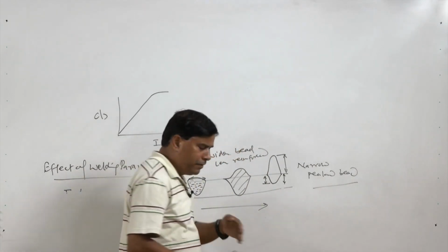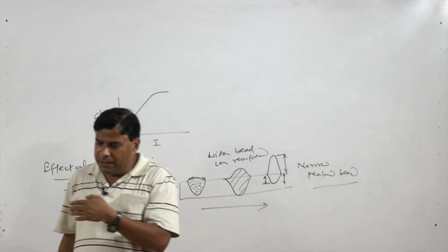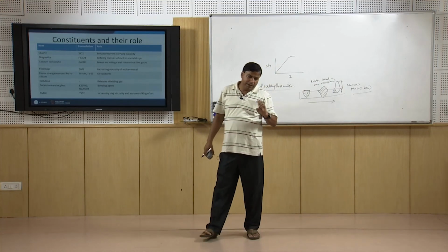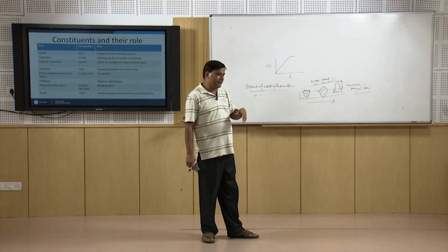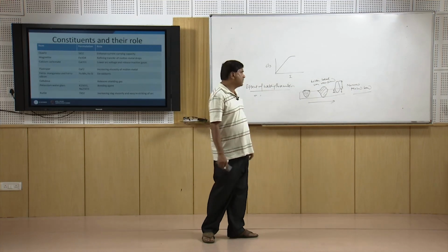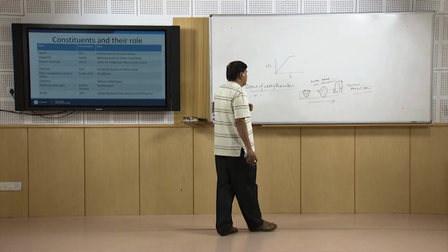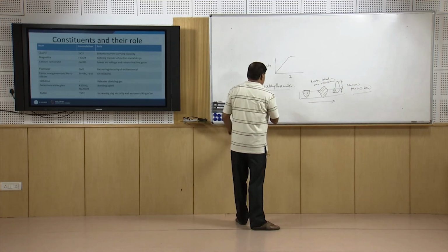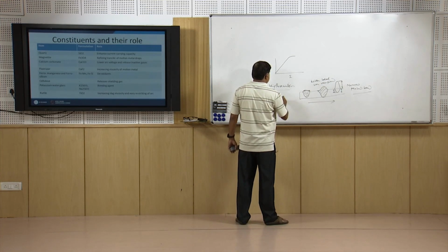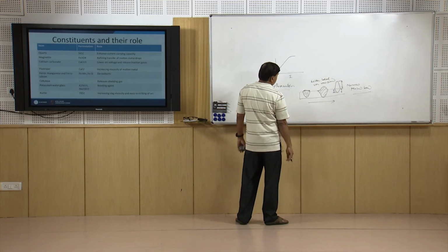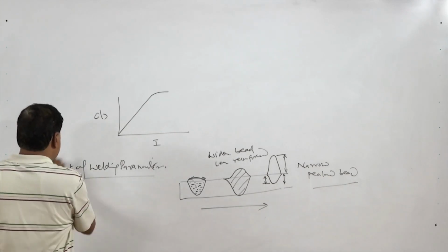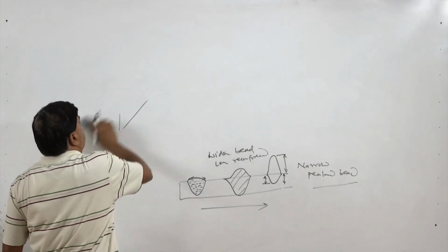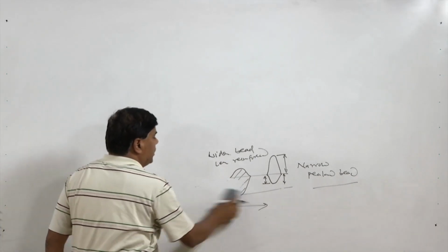And when we are moving very fast, then due to the high relative velocity with the ambient gases, it can deflect the arc, meaning arc blow can also take place. Sometimes undercut is also formed because just little melting takes place on both sides. So, near the toe of the weld, undercut is formed, which provides easy sites for stress concentration and can deteriorate the performance of the weld joint.